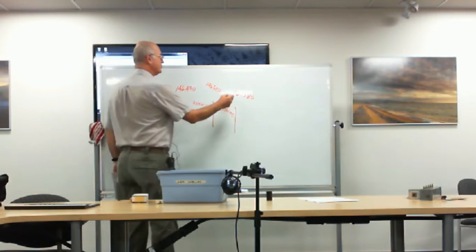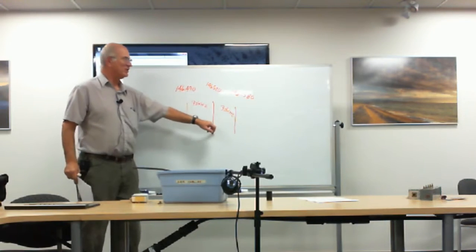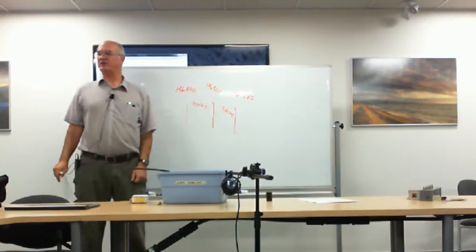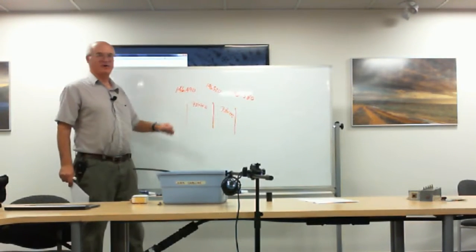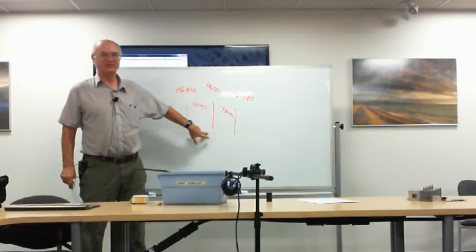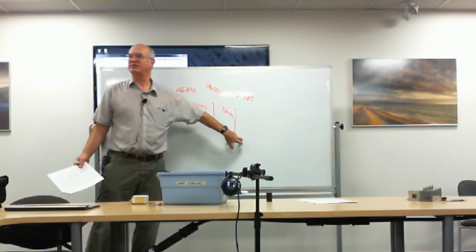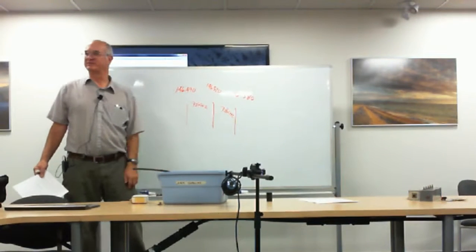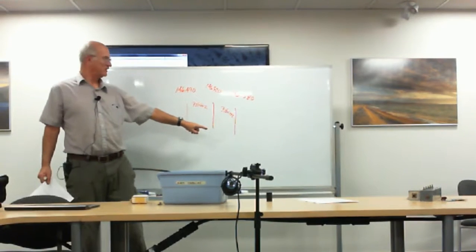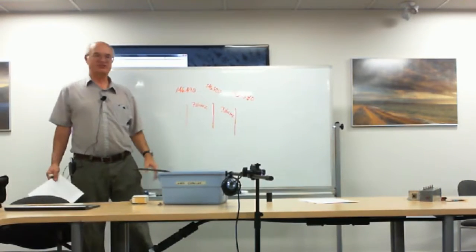Okay, you're having a nice little QSO with a friend on 14658. Somebody starts a QSO on 520. No problem. You're far enough away, you don't hear him. Well, he's transmitting. This guy keys up his transmitter. Guess what? You're going to hear both of these guys coming over top of what you're listening to. And if he's not transmitting at the time, they're going to sound like they're on your frequency. But as soon as one of these guys takes off his microphone, one of those frequencies disappears, like they weren't there again. And this is going to happen every time.